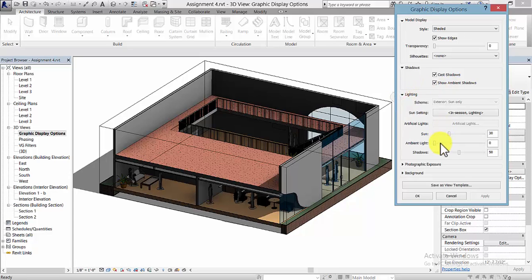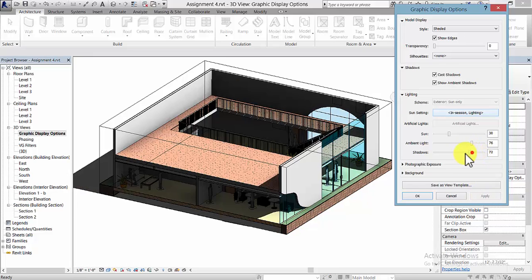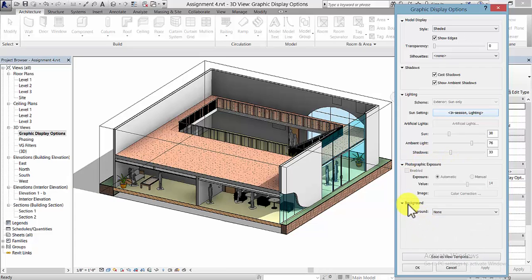And if we change the lighting, you'll see it even more, because one of the lighting options is ambient light. So I'll make that 100% and pick apply, so that you can see clearly with the ambient light, the shadows are cast around the geometry a little bit more, giving us a soft edge. We can intensify the shadows by using the slide bar, or taking them out so that you can have a different look.